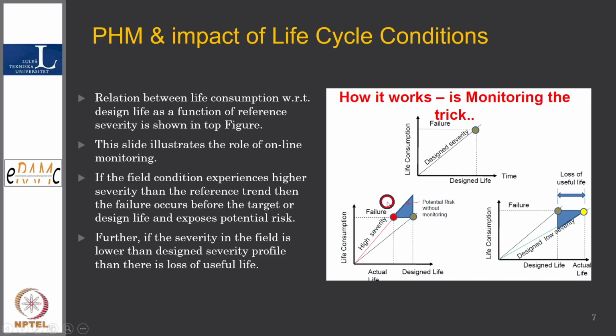If you see the normal bathtub curve, 50% of the area is there on the right side. So that means if somebody says you have to replace when MTTF has been reached, then we are losing this much life. It is a huge penalty, and it brings in a lot of plant interruption. So the good life of the component we have lost, and it is for everyone to imagine, depending on their system, what kind of compromise has been made.